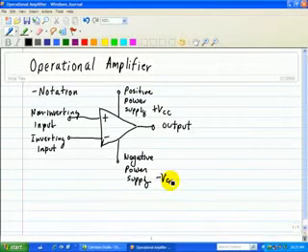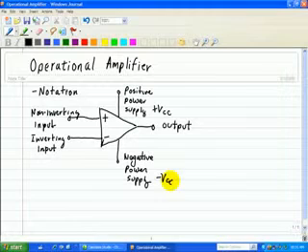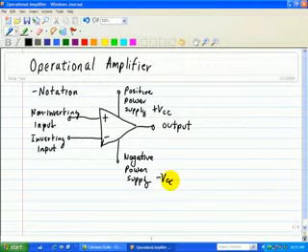While some op-amps have more than 5 terminals, these 5 are usually present and are the only ones we will use in this series of tutorial videos. The 2 power terminals shown here are not usually shown in circuit diagrams. However, be assured that they are always there because the external power supplies are required for the op-amp to operate as an active device.